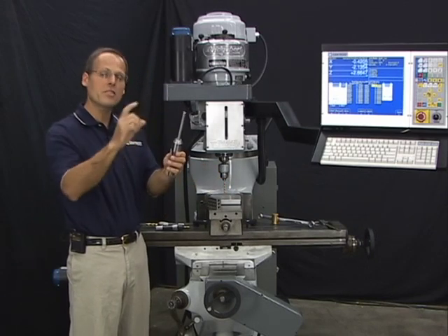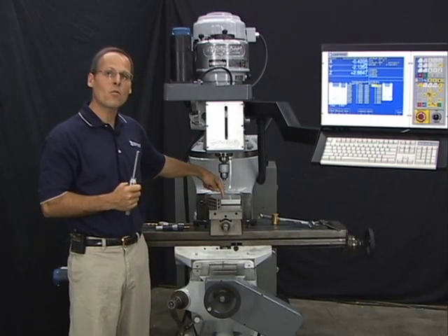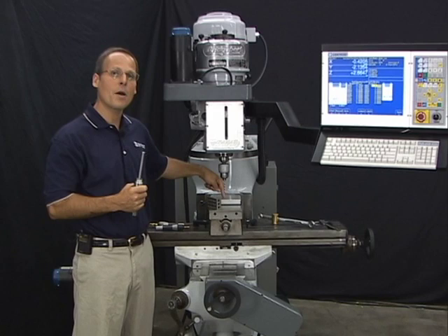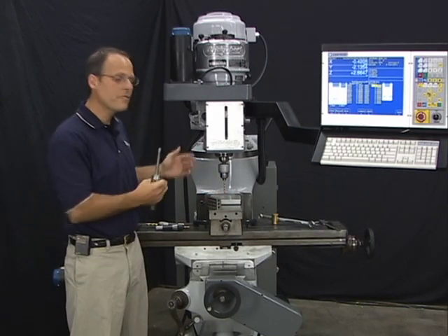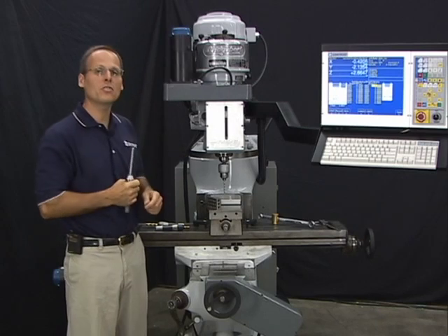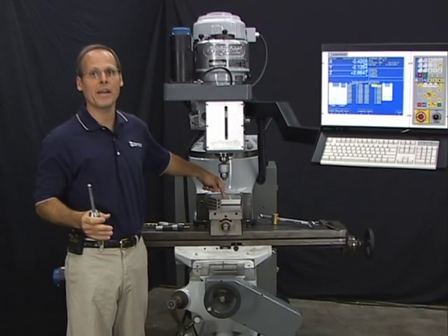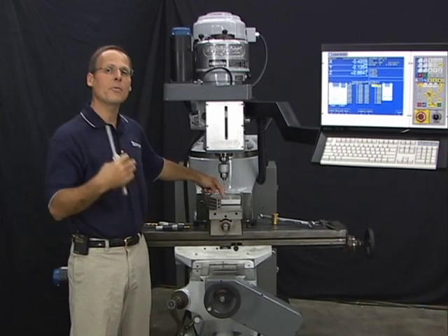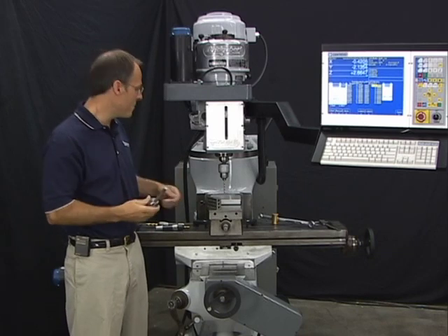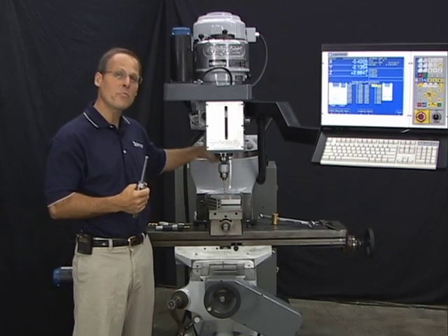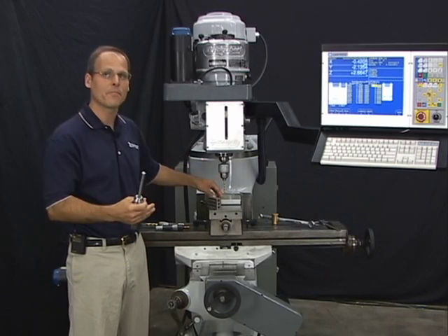As soon as I measure them against the reference tool, pick any one, set that one, use that one to set the top of your work, and all the other ones are automatically set. Load a different job, pick any one tool, use that tool to set the top of the work, all the other tools are automatically set. So every time I do a different part, it's saving me all that immense amount of setup time that I would have to do with the old method of setting off the top of the work zero each time.